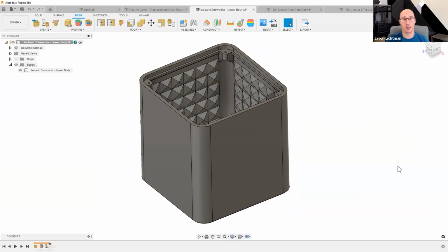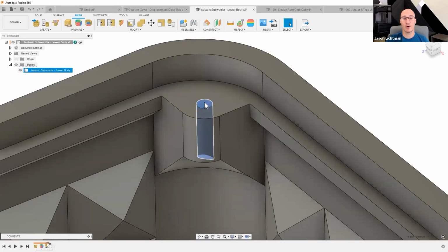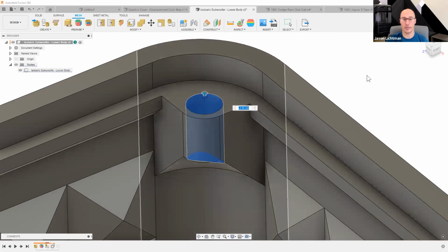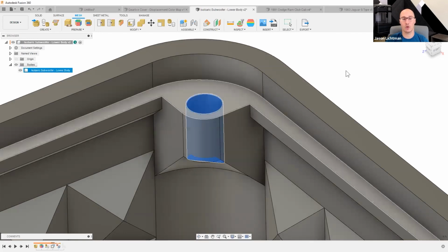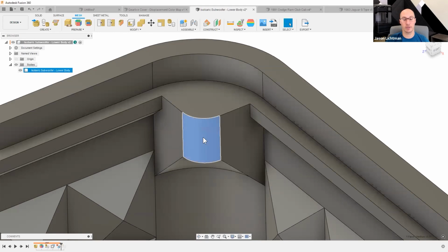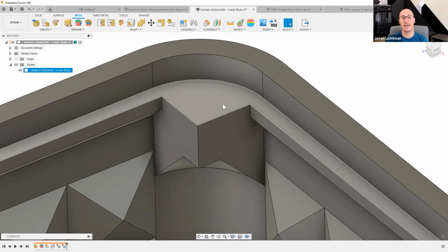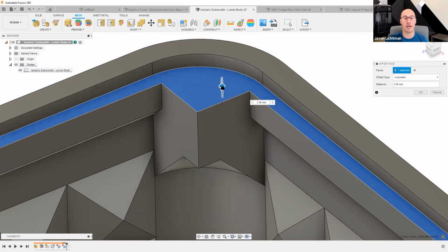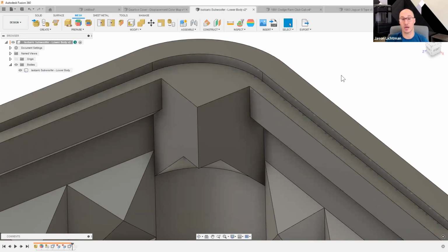And it is very much a clean body that is easy to work with relative to nearly any other option I could imagine receiving. And it's fantastic that I have something like this, because now I could zoom in on an area. If I want to make this hole bigger, I could go and make this hole bigger. If I want to get rid of the hole, I can select the hole and hit delete. If I want to get rid of the fillet, I can just hit delete. If I want to get this material to be taller, I could simply drag this however tall I would like.